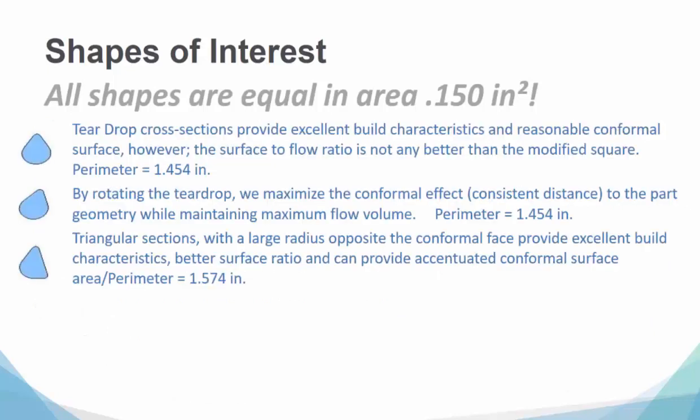As we've worked with printers, I've had the chance to talk to some people that have been metal printing for years now, and they made a comment to me I thought was pretty interesting about the teardrop shape. He said the teardrop shape came around because they first tried to print a round, and this is actually kind of how it came out. The horizontal has got flatter and flatter across the top, so it's harder and harder to print. So that's actually more the shape that they were seeing when they would cut the part open. So why not use it?